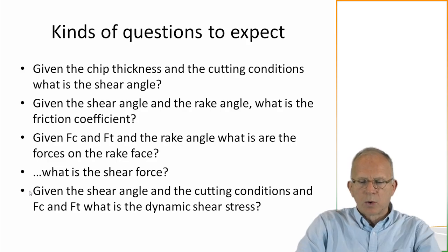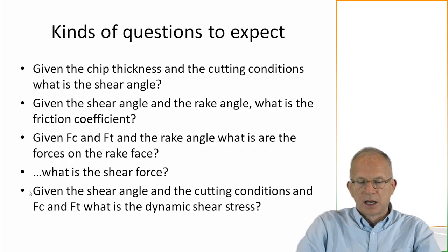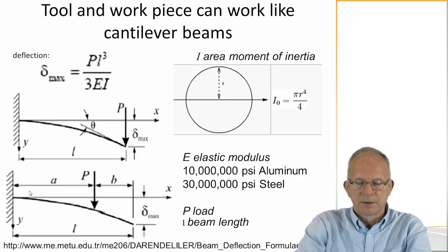So what kinds of questions should we expect to be able to answer now? Given the chip thickness and the cutting conditions, what's the shear angle and the rake angle, what's the friction coefficient? Given the cutting force and the thrust force and the rake angle, what are the forces on the rake face? What is the shear force? And given the shear angle and the cutting conditions in Fc and Ft, what is the dynamic shear stress? So these are kinds of questions that you could answer.